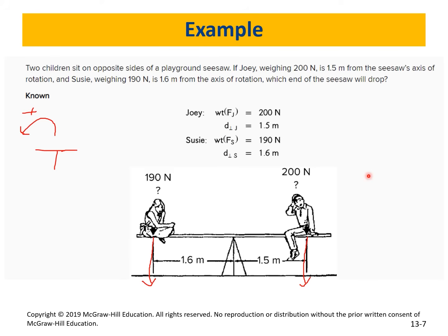And look, the moment arm is perpendicular to the line of action of the force. So you don't have to resolve because you have a 90-degree angle between the two, right? So it's a simple multiplication, that's all you need. You have a value? Which one? So that is correct.